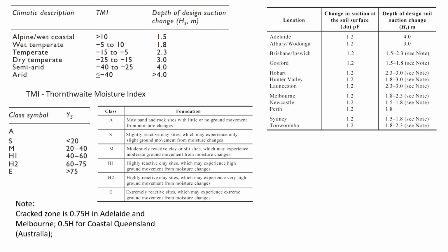Okay, this is the next slide. We'll show you why we're actually doing that. The whole idea is to better characterize the soil, and once we estimate the ground movements, usually it comes in millimeters. So these are the movements from our estimation. We can assign a class to the type of soil that we deal with, and based on that we will see if we need to do something about the soil, or actually that it's not really going to swell or shrink a lot.